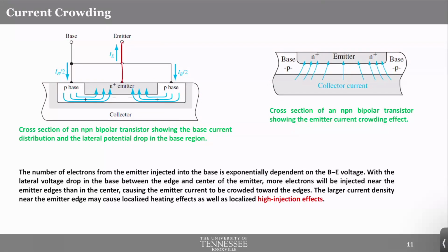Now this is an emitter, this is the emitter terminal. Base terminal, as you see it, this entire thing is the base terminal. So there are two connection points, but there could be more, doesn't matter. Both of these are base, basically. This one and this one, both of these are base. And you have one collector, and there is this big region underneath. That's the collector. Now, the point is, when electrons flow from emitter to collector, or current flows from collector to